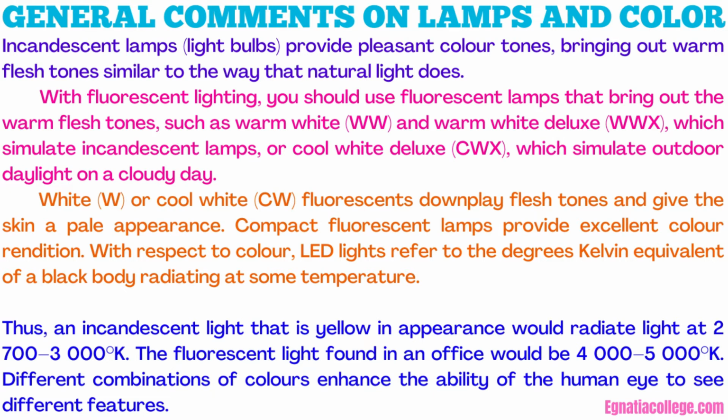General comments on lamps and color. Incandescent lamps, light bulbs, provide pleasant color tones, bringing out warm flesh tones similar to the way that natural light does. With fluorescent lighting, you should use fluorescent lamps that bring out the warm flesh tones, such as Warm White, WW, and Warm White Deluxe, WWX, which simulate incandescent lamps. Or Cool White Deluxe, CWX, which simulate outdoor daylight on a cloudy day. White, W, or Cool White, CW, fluorescents downplay flesh tones and give the skin a pale appearance. Compact fluorescent lamps provide excellent color rendition.